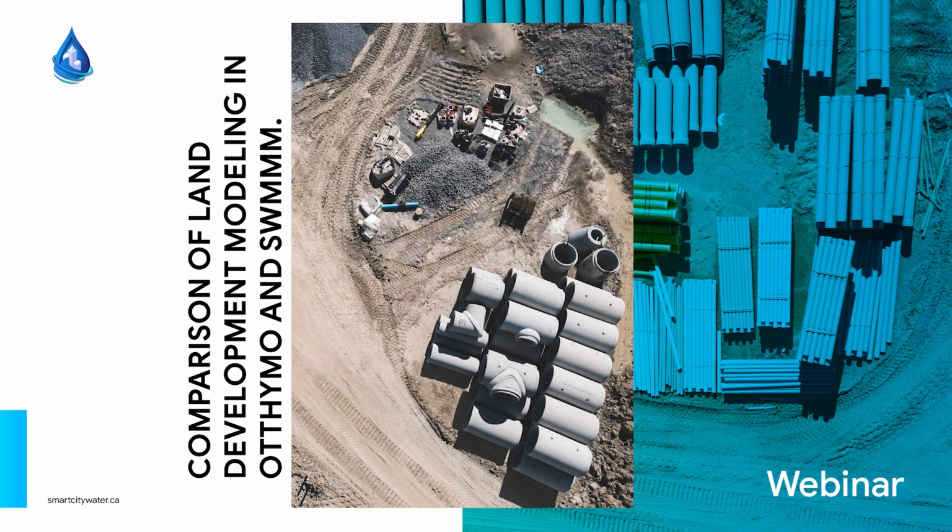But right now we're working on something so you can define the shape. You can define if it's a pyramid or a different shape, and give the dimensions. Then you can design the discharge by the orifice or weir. That's in OTTHYMO. But for the SWMM part, it's quite simple and straightforward. You can design the pond by its dimensions, and that's also coming in the new release. You can define the discharge by orifice, by rating curve, by weir, in both OTTHYMO and SWMM.